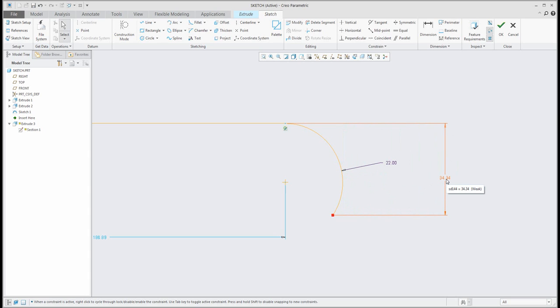This is the linear dimension, and the question is if we would like to create a different kind of dimension. You can select create the dimensions, select arc, then the 2 ends of the arc and the middle button. The system will create a new dimension for you, and this is the length of that curve, defined by length.